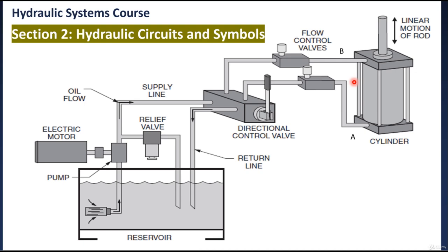And at the end, the leak-proof piping is also a very important item due to safety, environmental hazards, economical aspects, and to avoid any leakage of the hydraulic oil. Some other accessories such as flow control system, travel limit control, electrical motor starters, and overload protection may also be used in a hydraulic system to ensure system integrity.